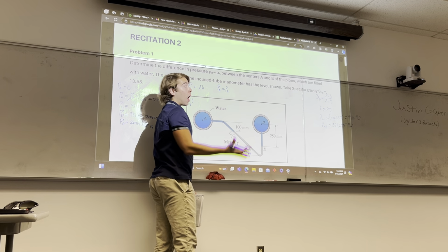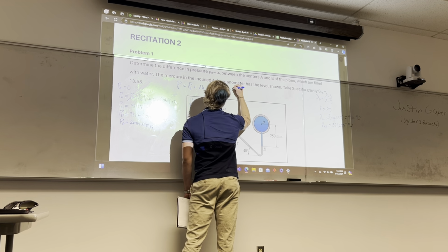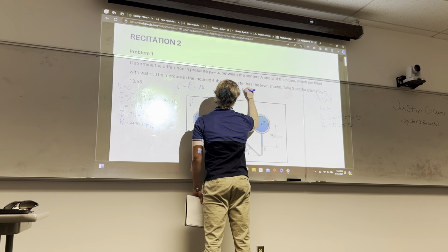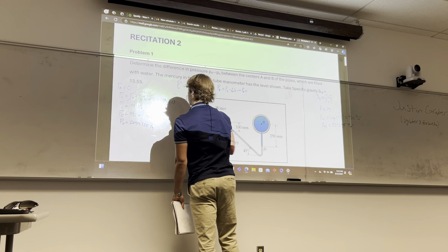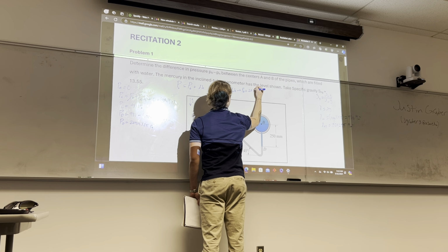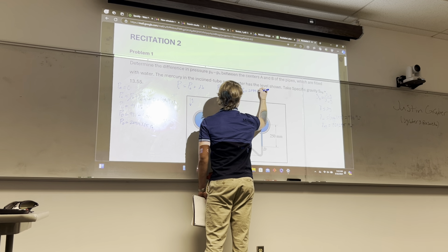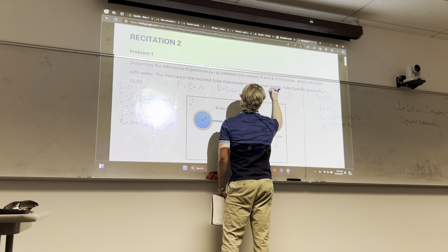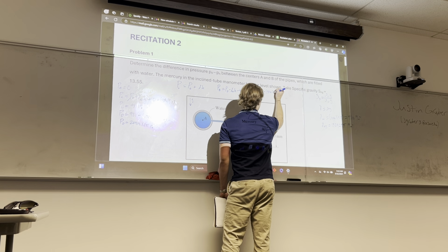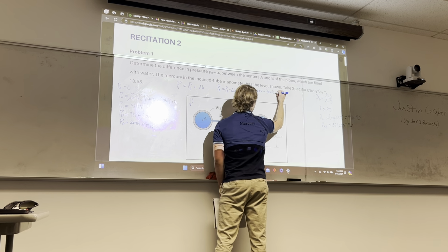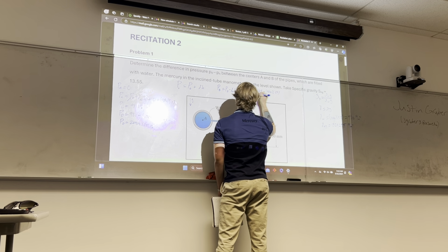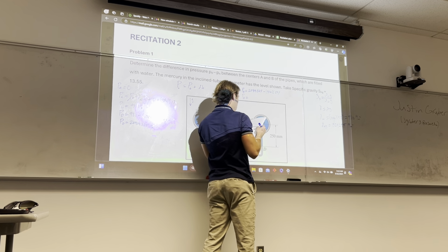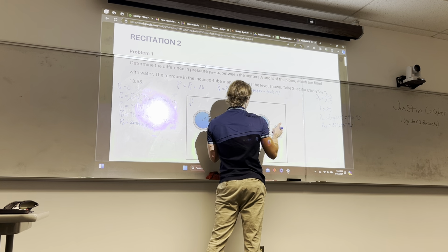Now we're going up, so we're going to subtract the amount of water, gamma times H. So we have PB equals that minus 9810 times just 0.25, so straight up. Okay, so we get PB equals 18,467 pascals.